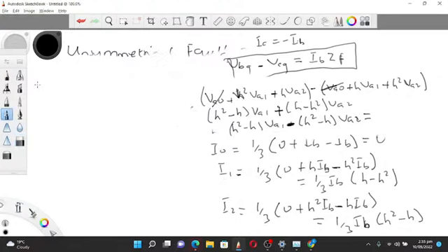Alright, now IB. I'm making reference to phase A. So IB can also be expressed as IA0 plus h squared IA1 plus h IA2. I hope we are all aware that this is what we have, from the voltage expression I wrote.